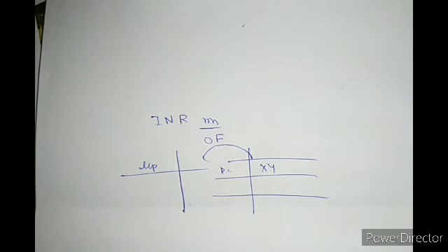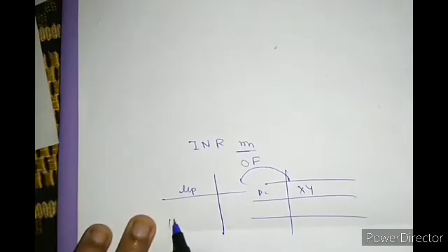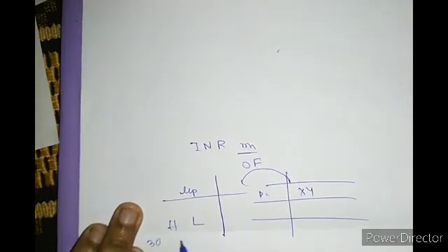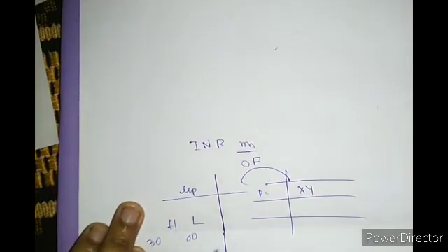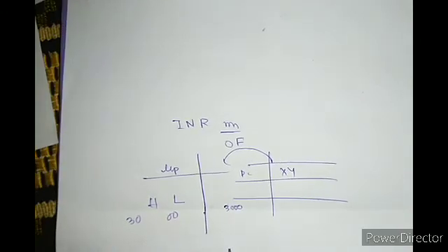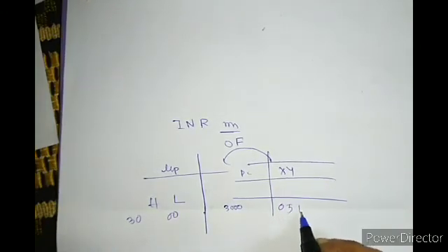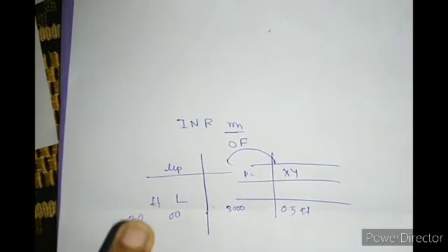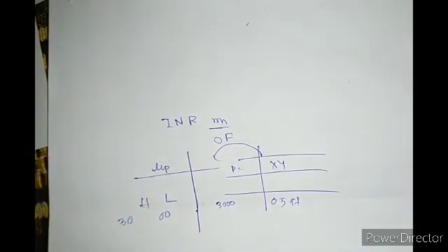So first I have to get the data, okay, probably in HL the address was 3000. According to my decoding, I have to get the data from location 3000, suppose 05H. After fetching and decoding are over, now it's time for execution. For execution, I have to get the data.